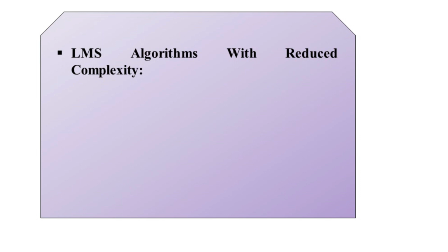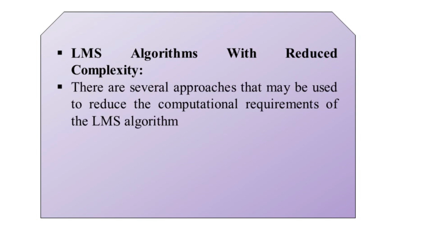There are several approaches that may be used to reduce the computational requirements of the LMS algorithm. One is the block LMS algorithm, which is identical to the LMS algorithm except that the filter coefficients are updated only once for each block of L samples.